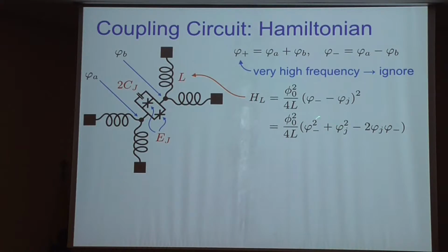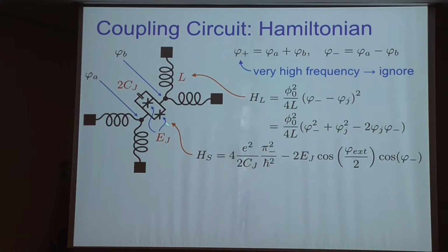And then I expand this so that I get the local terms and the coupling terms separated. And the squid itself also has a charging energy, which is due to the capacitance associated to each junction, and it has the Josephson energy. Now, what we do is choose the flux bias on the Josephson energy such that the constant part of the phase associated to it is high. Effectively, this means we suppress the critical currents in the squid. And then there's also an AC part, a time-dependent modulation on that.